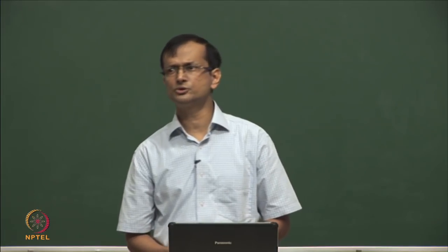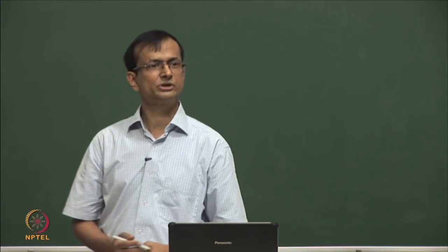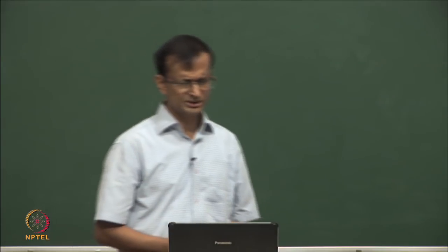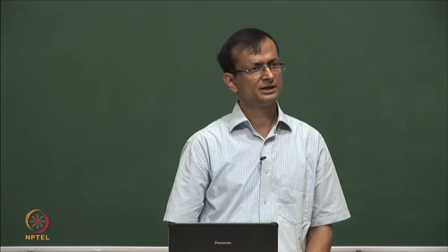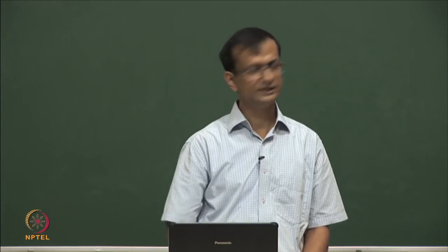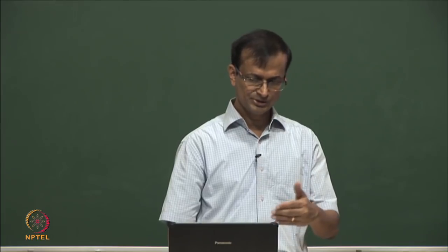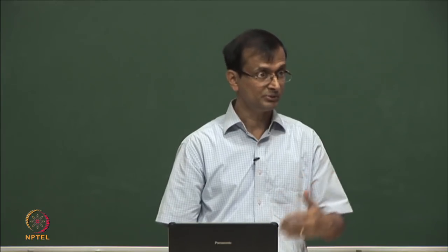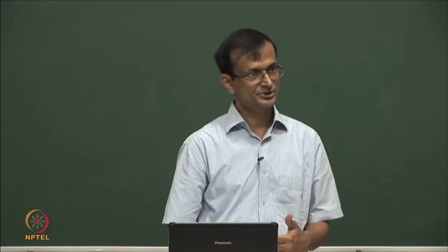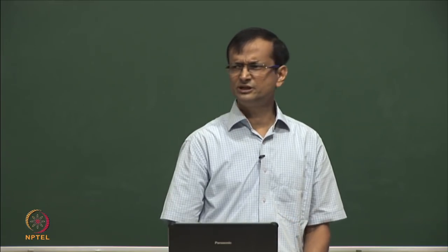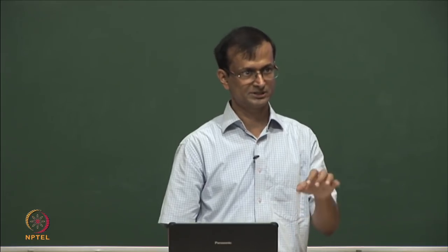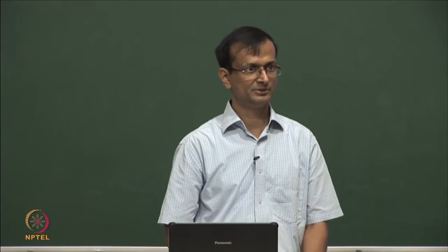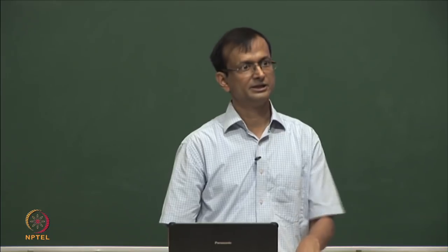It would usually be parameterized in some way, because it is hard to decide in advance what kind of muxes I should use. As it turned out, here I need a 2 to 1 mux, but if the level of sharing was 3-way, then I would need a 3 to 1 mux, right. So there would be different kinds: either I have 2 to 1, 4 to 1, 8 to 1 and so on, explicit discrete components of the muxes, which are there in the library.